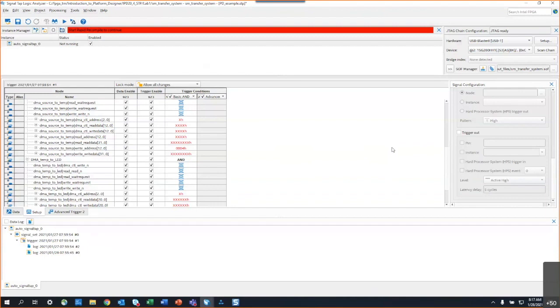Sorry, I'm getting my mega and kilohertz wrong. For the JTAG clock, it's basically just slowing it down. Yes, it's 24 megahertz down to 6 megahertz. Yeah, that's a common solution, and I don't know if it's a limitation with our JTAG interface or what.